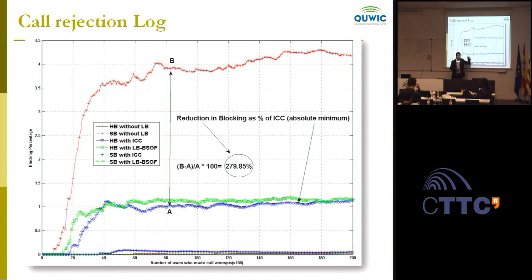But this is based on distributed supercell. In each supercell, it's just changing its own cell sizes within the supercell sectors to keep the number of users at the optimal value. The reason we chose this definition of supercell is that inter-sector handover is trivial. You don't have to do a lot of processing, you don't have to do signaling, and it's not an overhead on the core network either. So if you can afford inter-sector handover, you are able to reduce your blocking substantially.